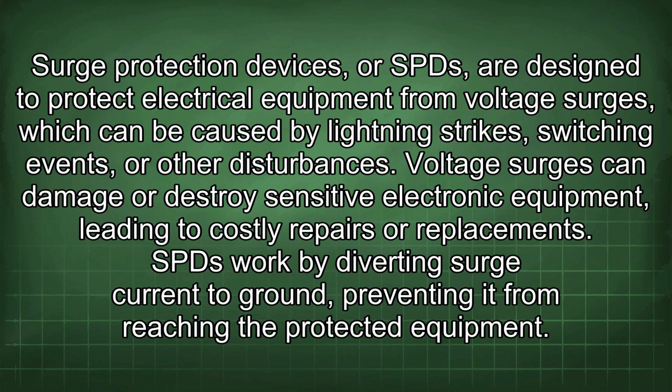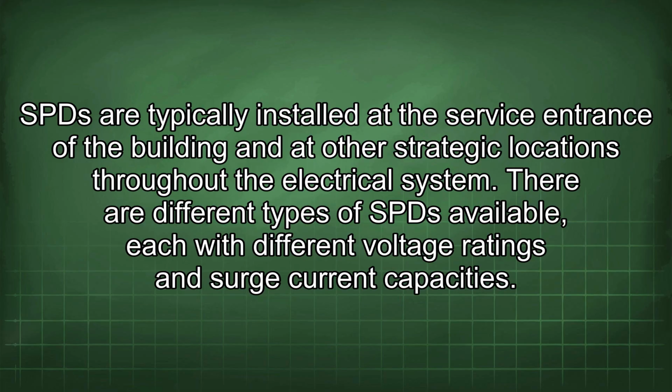Surge protection devices, or SPDs, are designed to protect electrical equipment from voltage surges, which can be caused by lightning strikes, switching events, or other disturbances. Voltage surges can damage or destroy sensitive electronic equipment, leading to costly repairs or replacements. SPDs work by diverting surge current to ground, preventing it from reaching the protected equipment. SPDs are typically installed at the service entrance of the building and at other strategic locations throughout the electrical system. There are different types of SPDs available, each with different voltage ratings and surge current capacities.